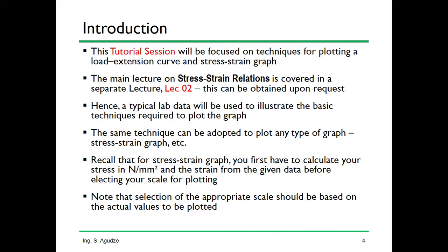Is that right? And then you have to select an appropriate scale based on the values you plot. If it is a load extension, you are going to plot the load against extension. But if it is stress strain, you are going to plot stress and strain. So make sure your scale is based on the actual values you'll be plotting.